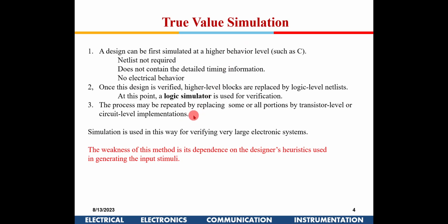This will run quicker because this doesn't take into consideration the delays, parasitics, and capacitances involved in the transistors, or the currents actually available in those transistors and things like that. It will just do it quickly. So this is the first step, right? So if you do this, and then only we move forward.